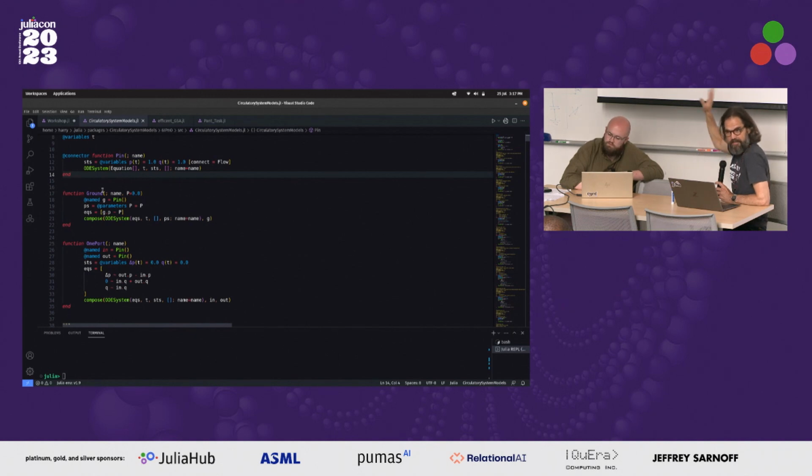So just read the tilde as an equals if you write out your equations. So we have the equation delta P is out P minus in P, which gives you a negative pressure over the element, which is different to what we would do in the electrical analogy, where you have the potential in minus out. So keep in mind that delta P is usually negative. And in this case, it's not a compliant element, this one port.